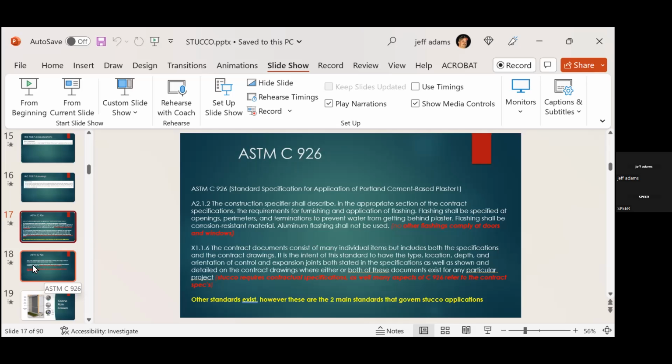And we use the word expansion joints, but control joints are also permissible, and that's mostly what we use in Texas, a single control joint. It does not expand and contract as much. It's still an expansion joint. It does say in there that a control joint is to help with expansion and contraction. So it is theoretically still an expansion type of joint.